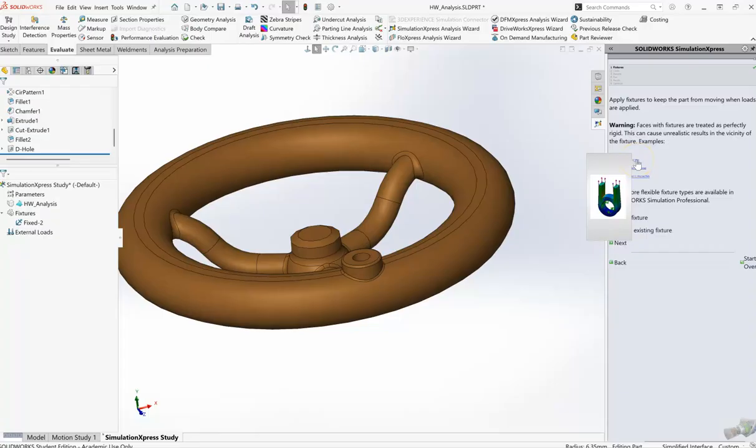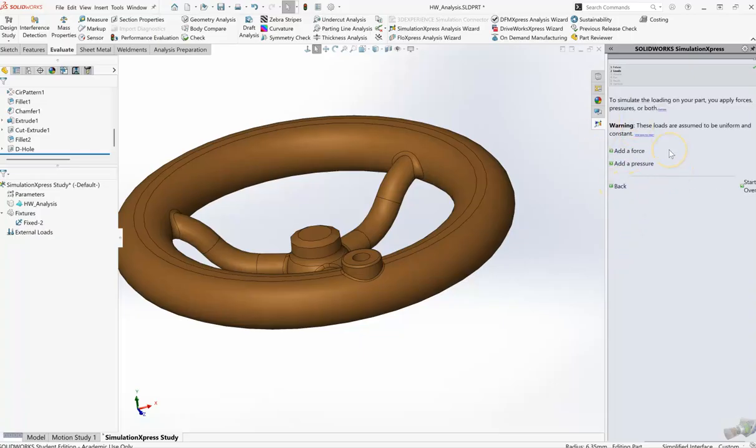We're going to move on, and you can hover over these, and this shows you some examples of when we fix different areas on the part. This is like if we fix faces, and you can see a load pulling up. Here it shows the load and where they're making the end of the shaft fixed. Then here they're making that plate fixed, say to a wall, and fastening it with fasteners, and putting a force on trying to pull that thing away. That plate's supposed to be fixed, but you can see where it was bending. Now we're going to go next.